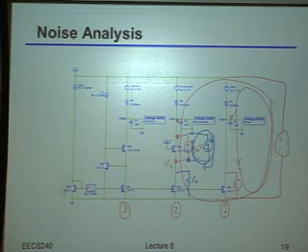Okay? Now, it turns out that's obviously not 100% true, because there's always an ro here, so some percentage of the cascode current will flow through there. And in particular, there's always going to be some parasitic capacitance at that node. That means that at higher frequencies, more of the cascode current will tend to flow through that capacitance, and therefore through the output, and cause some additional noise. But as long as you keep that capacitance small, which by the way you really do want to do for many, many reasons, including some of these settling things we talked about before, then this cascode structure will not add a whole lot of noise to your output.